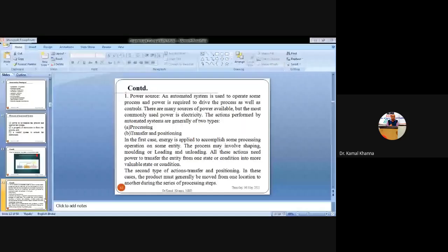In the case of the lathe machines, the specimen is always moving, in a rotating position, whereas the tool is fixed, but it is vice versa in the case of the milling or the drilling machines.